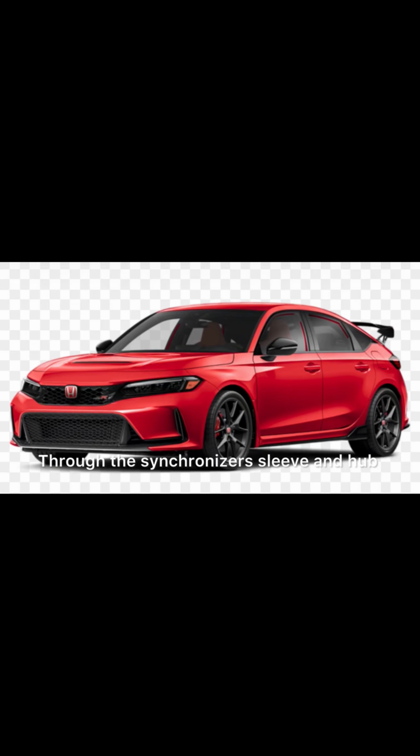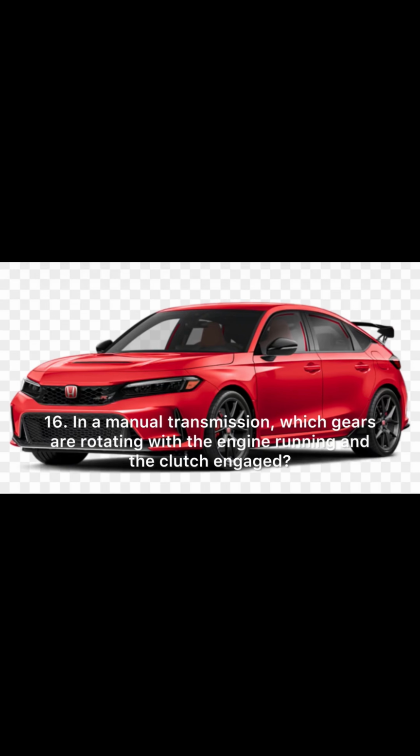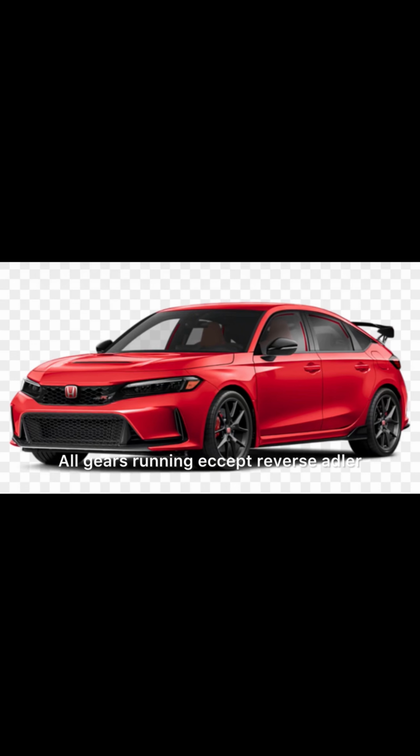Through the synchronizer's sleeve and hub. 16. In a manual transmission, which gears are rotating with the engine running and the clutch engaged? All gears running except reverse idler. Objective 3: gear designs, ratios and torque.